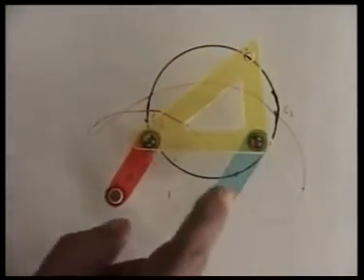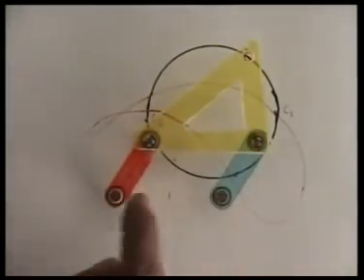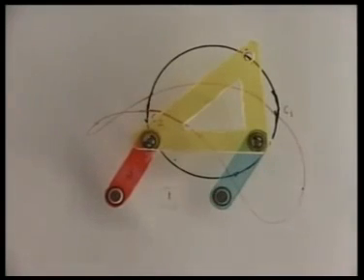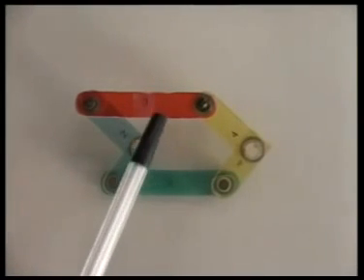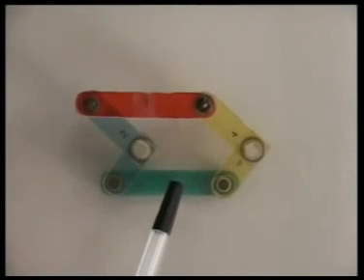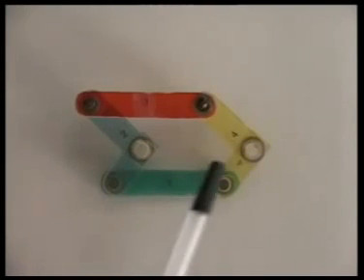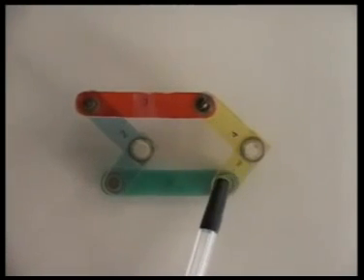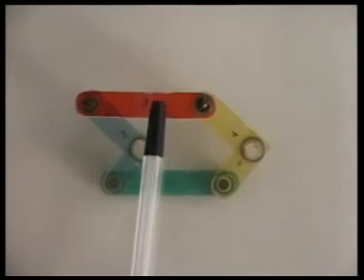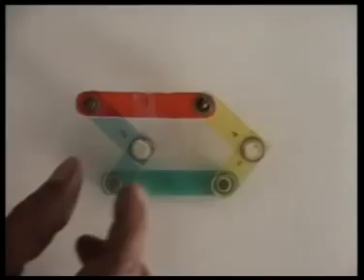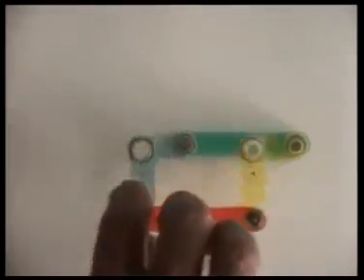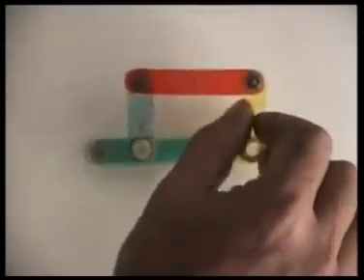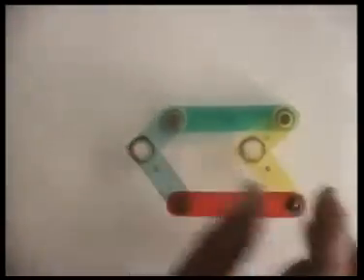So, to get rid of this uncertain configuration, it is better to have an extra coupler as explained earlier, and we shall demonstrate it through our next model. Let us now look at the model of this parallelogram linkage with a redundant coupler. As we see, these two links are extended at 90 degrees and there are two parallel couplers. Consequently, here we should be able to maintain the parallelogram configuration throughout the cycle of motion. It can never flip back into anti-parallelogram configuration.